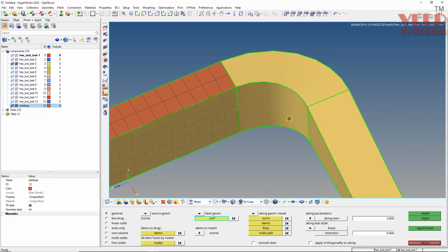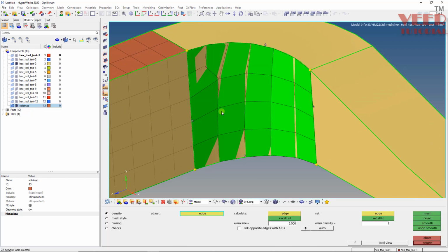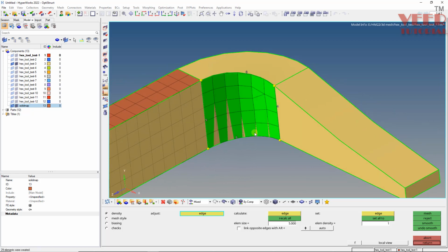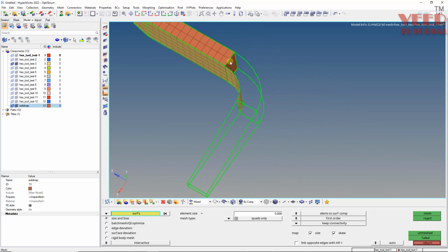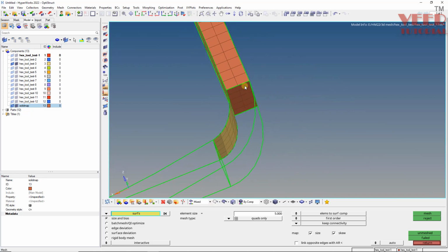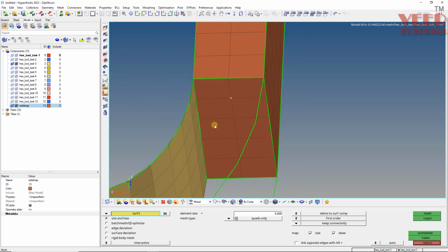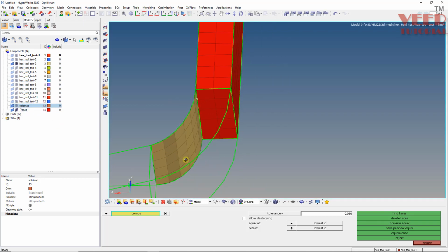Now I will have to do the mesh here. First I will go to F12, select the surface mesh. Let's say if I select equal number of element here, no problem. Now in the along I also need these elements, but we cannot take the solid element as the guiding element, so we need to extract the faces. Go to X and click on this solid map, find. So it finds the faces. Now I will hide the solid map.